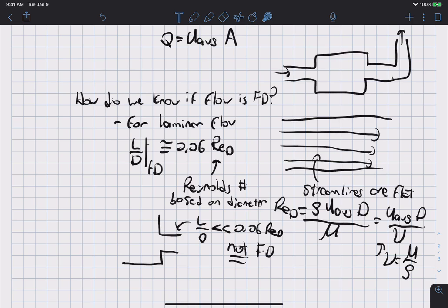and you cannot use, in such a situation, the analysis techniques that we're learning in this class. It becomes much more complicated because you need to account for those boundary layers and things like that that are going to be developing but not fully merging, and they're going to dominate the characteristics of the flow, and it's going to be complicated.